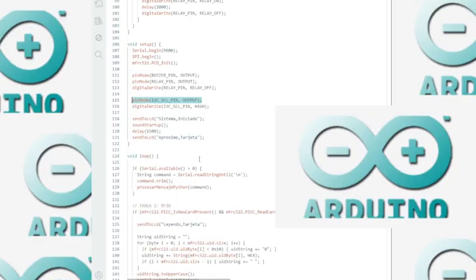The loop is the heart of the logic. It functions as a polling cycle. mfrc522.PICC_IsNewCardPresent sends an RF request REQA to check for cards.